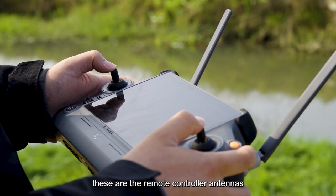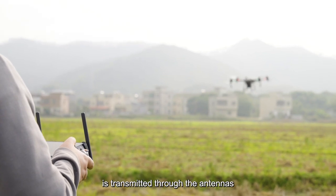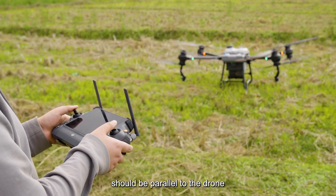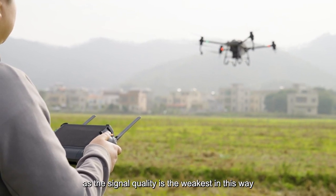These are the remote controller antennas. The signal between the remote controller and the aircraft is transmitted through the antennas. But remember that the remote controller antennas should be parallel to the drone, rather than point to the drone, as the signal quality is the weakest in this way.